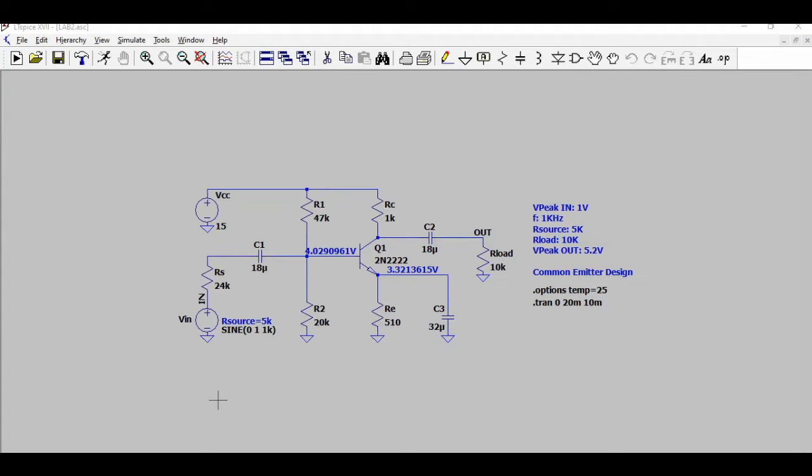Well, firstly, I will explain the operation of the circuit. We first place the common emitter amplifier that generates the voltage gain, and then we have the common collector that generates the current gain. The common emitter provides us with the amplified signal and a high output impedance, while the common collector configuration ensures that the output impedance is low and greater current gain is produced. In this way, we avoid the effect of the load.